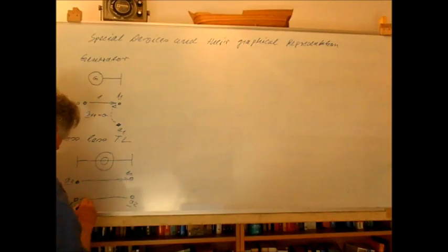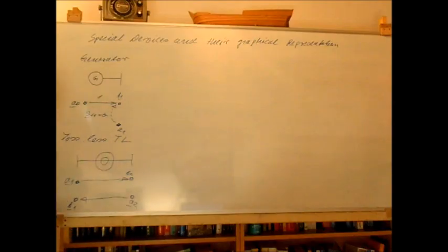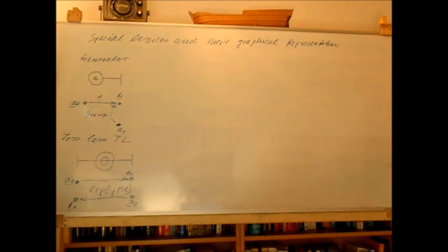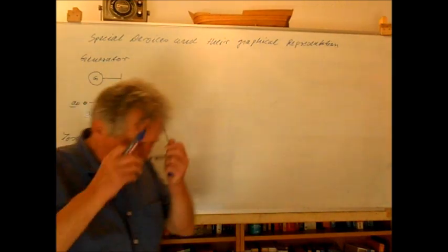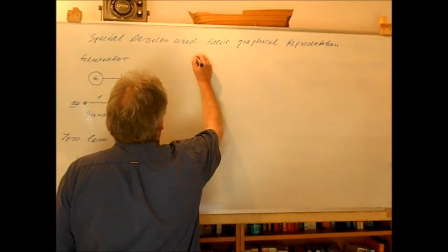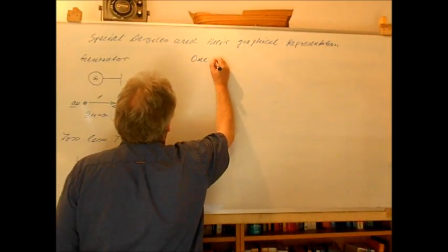So we already know that the transmission line is an element free of self-reflection. Here we will just have the exponential of minus j beta times L, which describes the phase shift due to the transmission line. A special application further is a so-called one-way